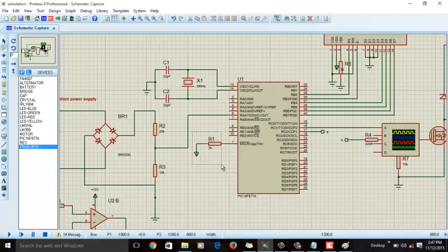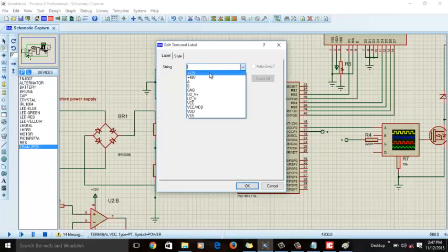This circuit is for the MCLR button, just like the restart button of your computer. If you push the button, the microcontroller will restart, but we don't need that, so I just connected a logic high with it. It means whenever you turn it on, it will remain turned on and will not be turned off. So you have to connect 5 volt here.